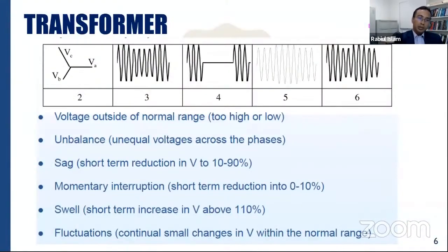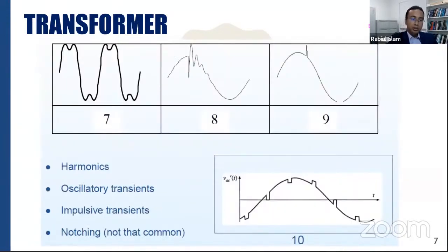On the other hand, if we look at the power quality or the issues with our power networks, how good is the quality of our grid power, right? In many countries, especially in Asian countries, I know the grid power is still not in very good quality. That means voltage sag, voltage swell, and definitely some other issues over there. Voltage unbalance, and also harmonics, oscillatory transients, impulsive transients, and noise. So those problems are very common in our existing power networks, right?